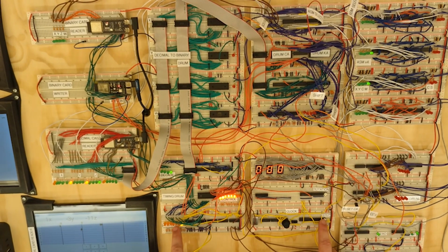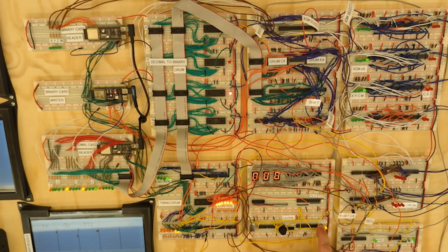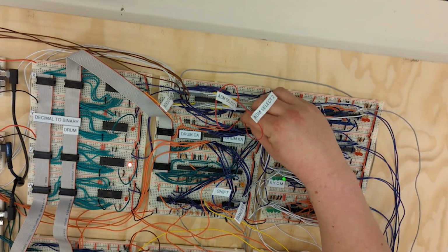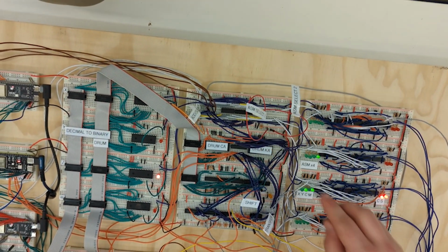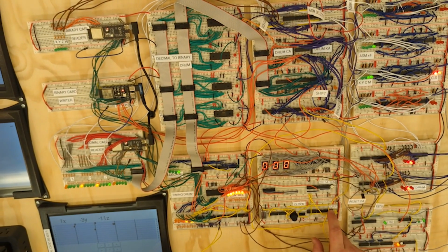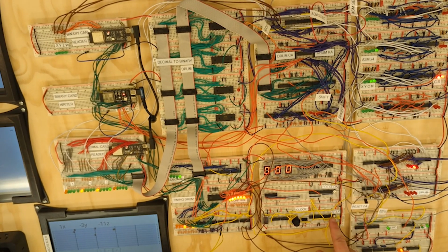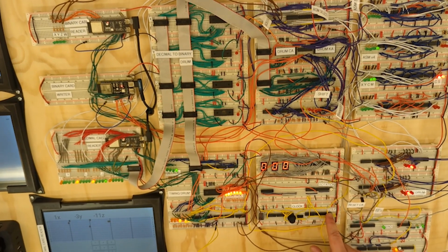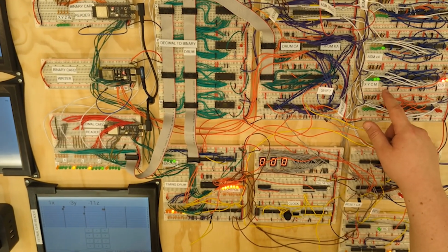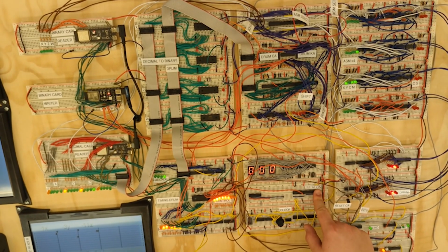So we see at address 0, we have nothing because the first bit of 10 is 0. Then the next one is 1. So let me make sure we have our select lines enabled so that we see that 1 reflected in the adders there. 0, and then the 1 again. Now, since this is a negative number stored in 2's complement, the resulting additions will have a borrow bit that will make all the rest of the bits in the number 1.